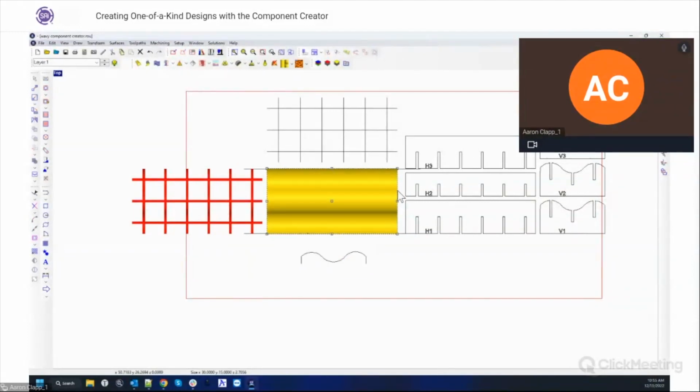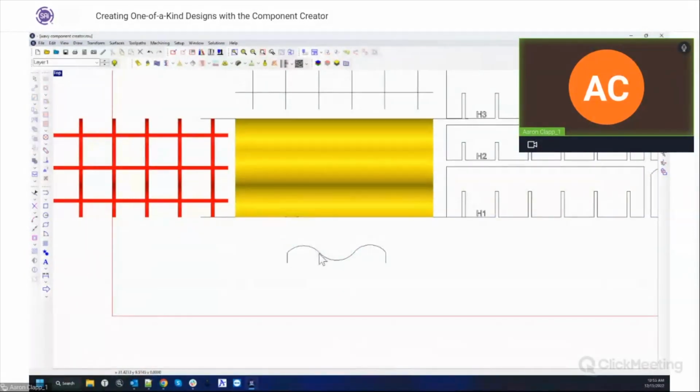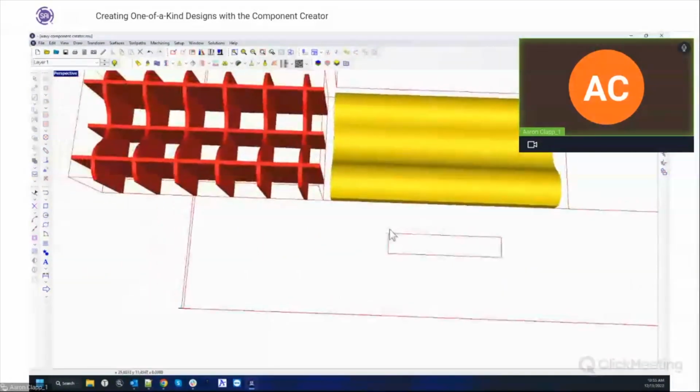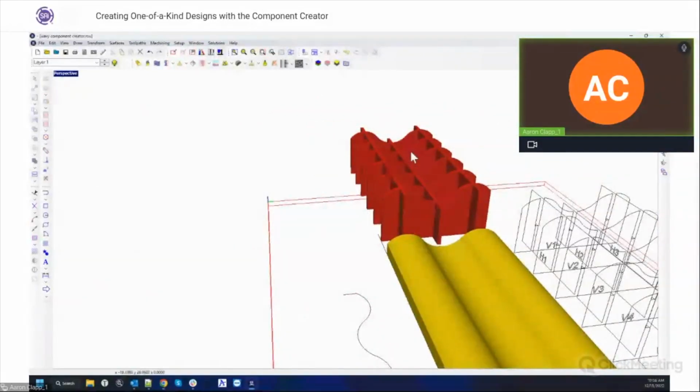So if we click on this and go to F2, I made my relief 30 by 15. And if I click on my profile, I made it exactly 15 tall. The width in this case doesn't really matter, but I made it exactly 15. And when I created the arc, I did 3 equal sections. So this distance here to here, here to here, and here to here were all equidistant. So they're all equal to each other, and that's how I was able to get that to land right in the middle. So just a little more attention to detail there, but you can get that to look really nice and sharp. Those lines land in the perfect spot to create this unique shelf.